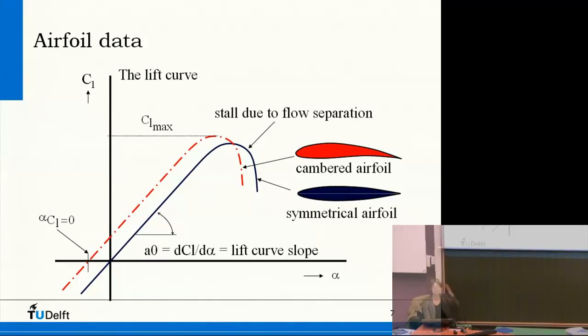You can imagine if you have 90 degrees of angle of attack, you know quite well that the flow doesn't really follow the object anymore, but you get separation here at both sides and the dead water region behind. You see that if you hold your hand inside a river or so. So of course, that is fully separated from leading edge to trailing edge. So somewhere in between the attached flow, in that case, the flow will start to separate. And that is here. And that phenomenon is called stall.